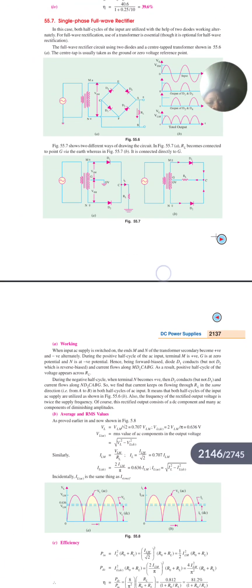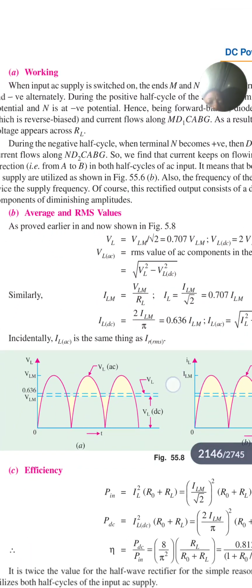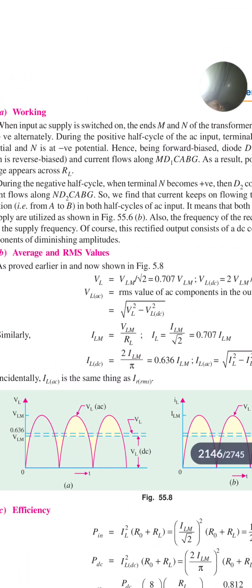So now you see there is not much difference. I just want to break this down. Now for the RMS, the half wave is just, from the word half, meaning they divided the full wave by 2. So now when you see those IDC equals IM over pi, you now multiply it by 2, then you have your IDC for the full wave. For the center tap and the full bridge, I have the same calculation.